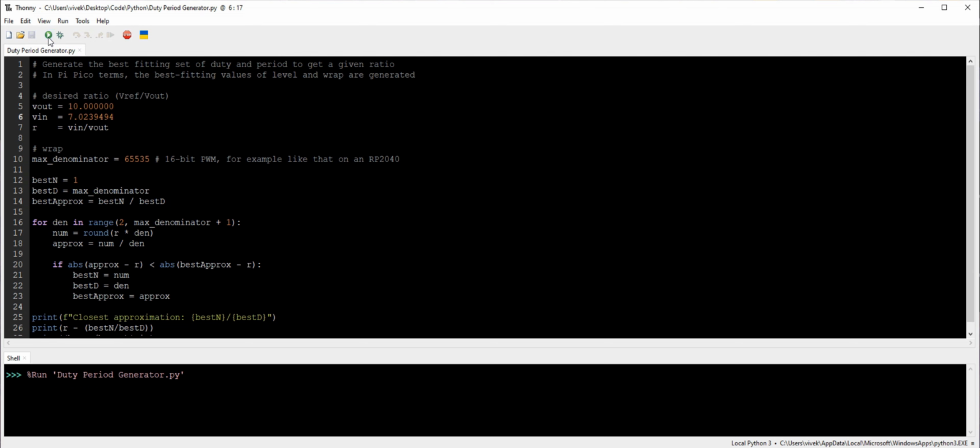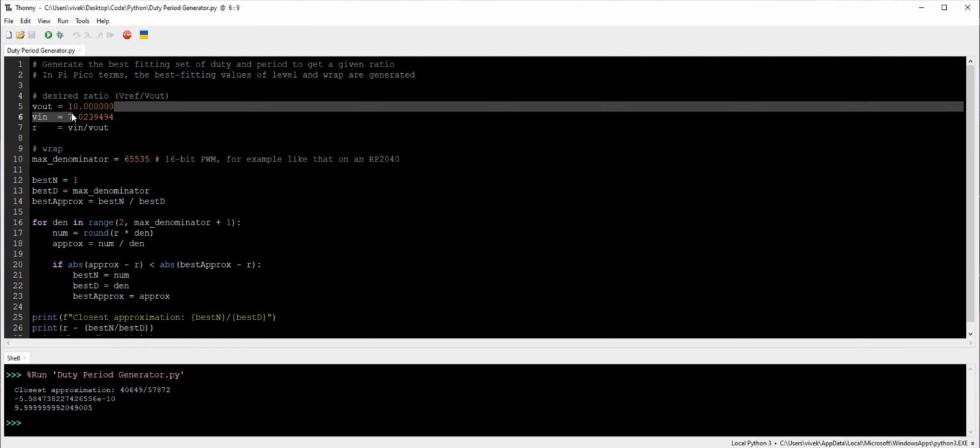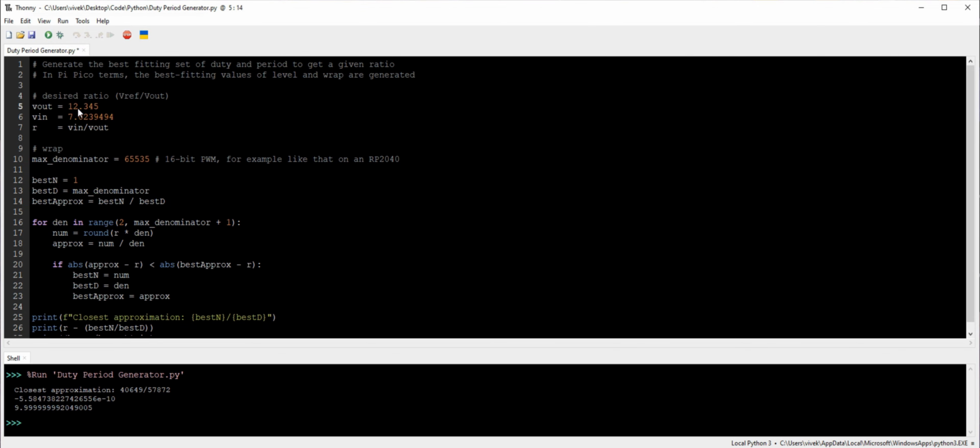The way the code is written also generates the values with the least possible denominator. So in terms of PWM, the highest possible PWM frequency with a given duty cycle is generated. Given the effectiveness of this method, I was curious to see how well it would perform as a DAC.